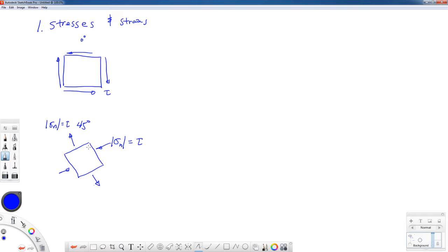So the interesting thing is, as we sweep from 0 to 90 degrees for theta, we're going to get different values of both normal and shearing stress. At 45 degrees, the shearing stresses all vanish, and we have tension and compression at 90-degree angles. If we look at this block, it kind of makes sense.